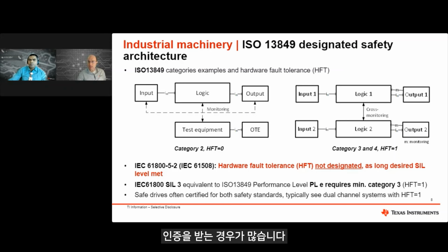Now, we get our safety-enabled industrial drive with safe torque off support. In that case, we should show a dual-channel system, STOA and STOB. To add safe motion functions, like safe limited speed, safe limited torque, or safe stop 2, it typically requires safety MCUs. A typical approach is extended safety modules with dual MCUs which cross-monitor each other. In case of a fault in one of the safety MCUs, the system will trigger STO to get into a safe state.